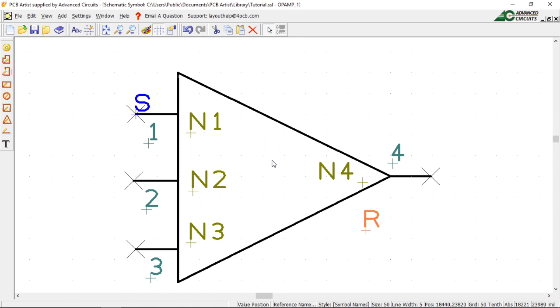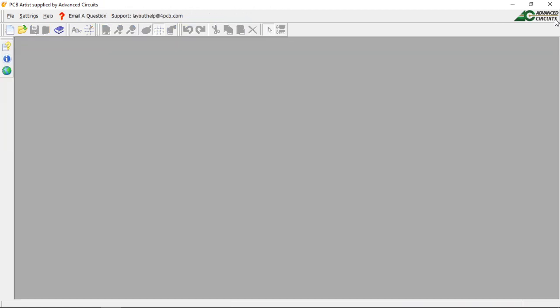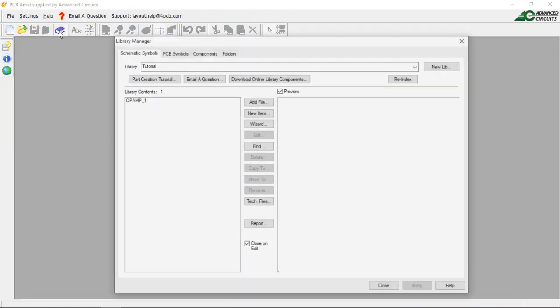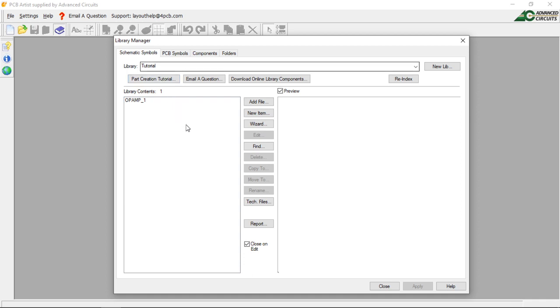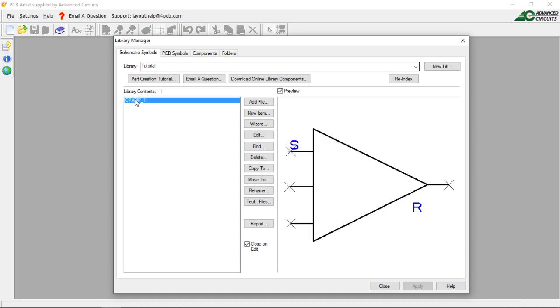And let's see, is there anything else we want to do? Well, we can just go ahead and close it. So let's go ahead and close this. So go over to here and click X, and let's bring this back up. It's schematic, it's op amp. So notice there's only one symbol here. There could be a whole bunch. And so let's click op amp, and there it is.